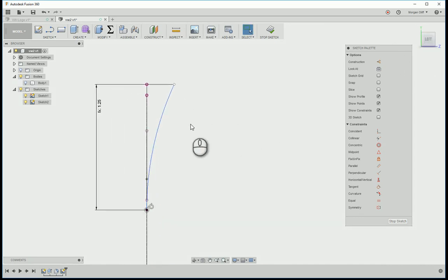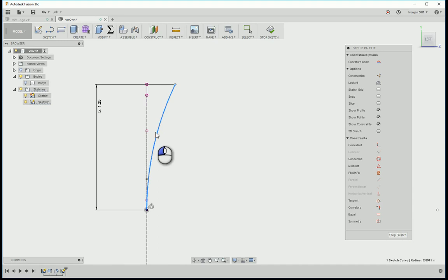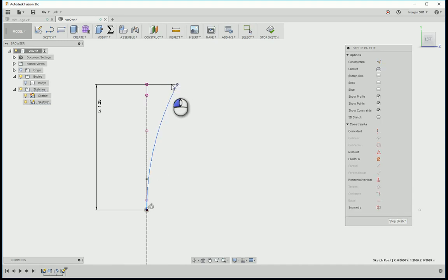And this is not fully defined yet because we let it snap tangent. That's good. So we want to call out this radius, and if that's 3, that's close enough to D1. We'll say D1. And that way everything stays locked nice and proportionate. Then we can do L for line here, and then another L for line. You could put this way or flat, but you'll see what I'm up to here in a second.